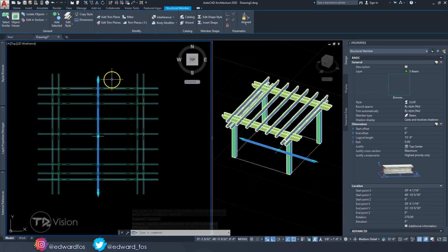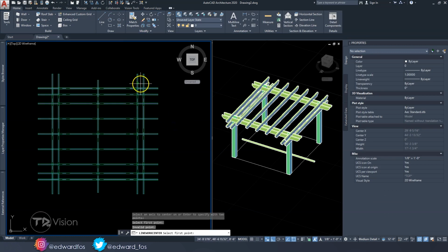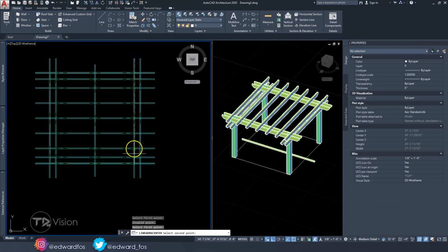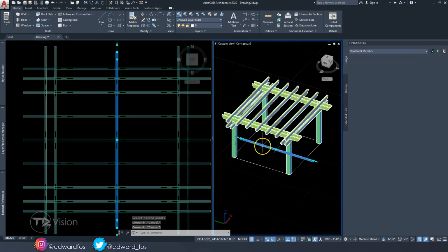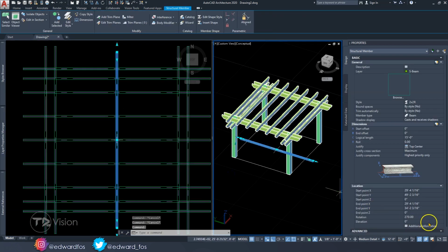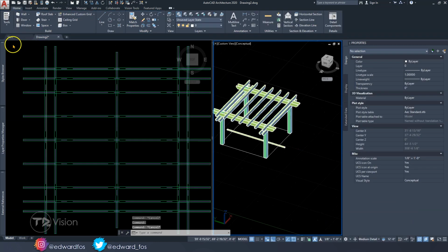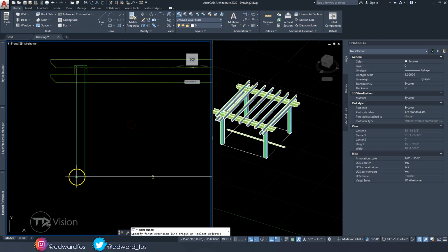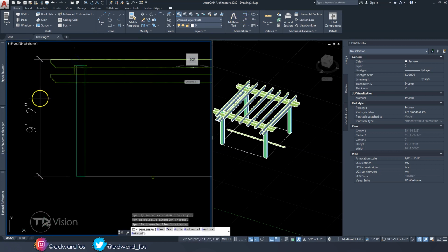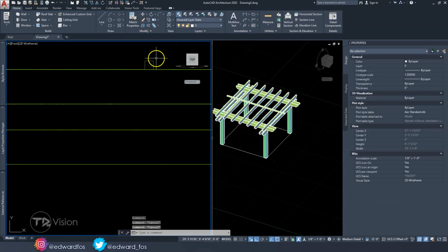And that looks good. I don't think it is centered. So I'm going to go to my center command and make sure that it is centered within this space here. Now, if you notice here, it is on the floor, and that's not good. So I'm going to raise this up to whatever distance I need to raise it up. Let's go to the front view and see what that looks like. Front. Let's take a measurement from base to the top. So this needs to be raised up 9'4", like that, to sit on top.